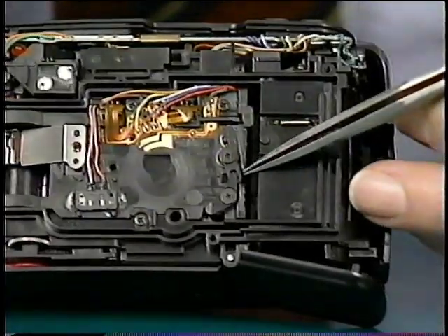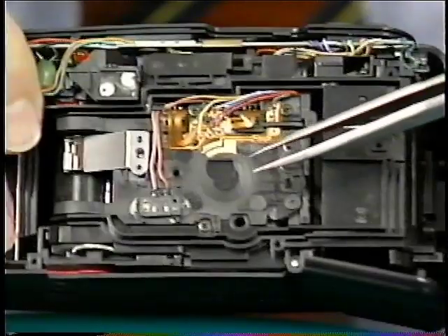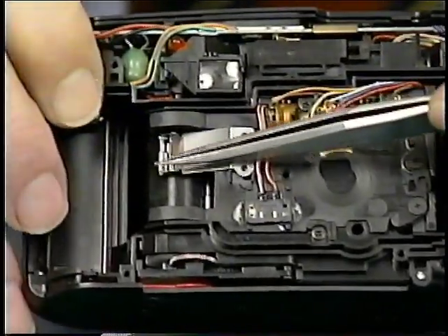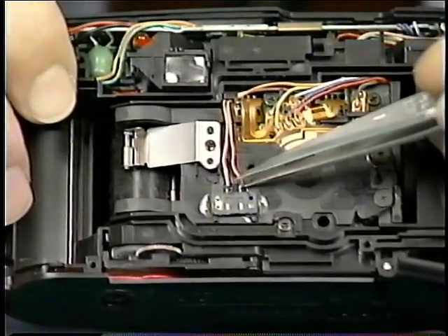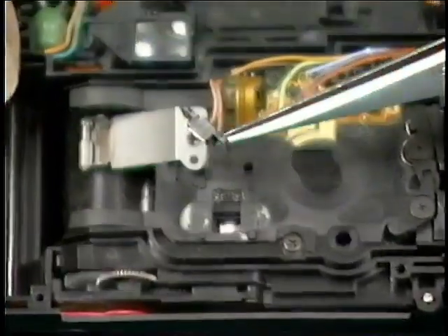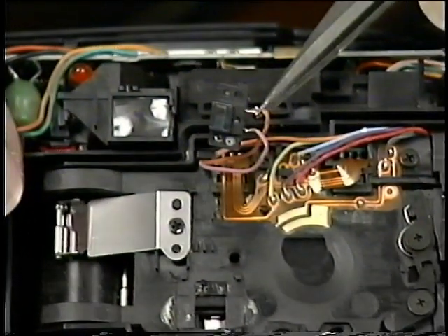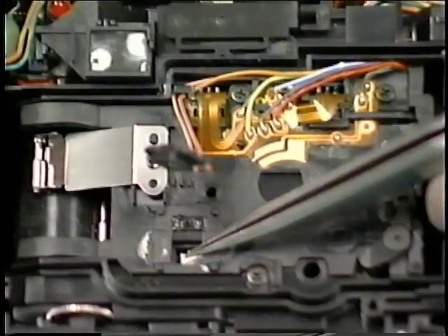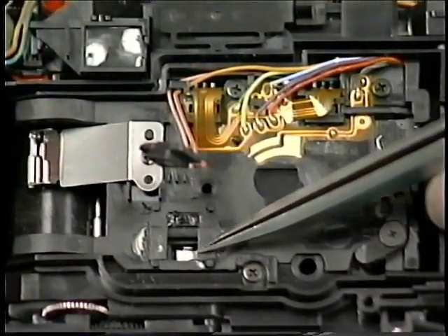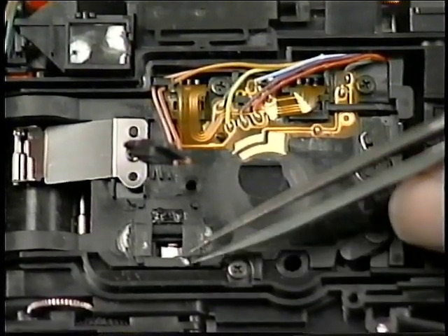The film cassette is over here. The film runs underneath this pressure plate, and the spool or take-up spool side is over here. This is the magnetic head, and we've detached that so you can see it, but it's a small tape recorder type head that imprints a code along the bottom edge of the film on the back side where the magnetic coating is, and that tells the processor print format and date.